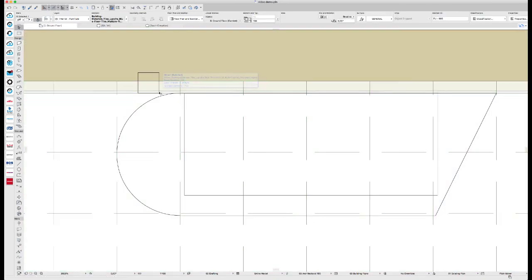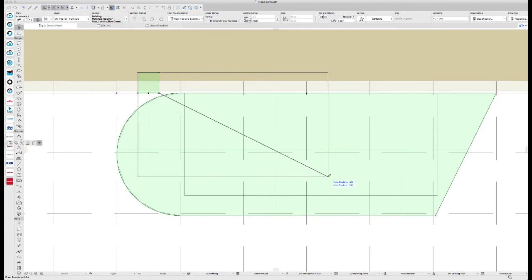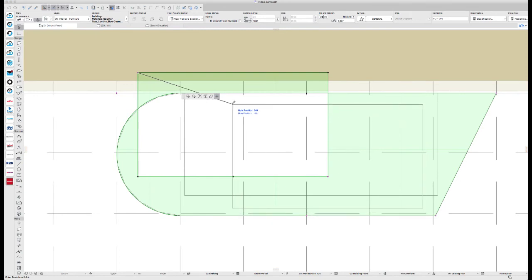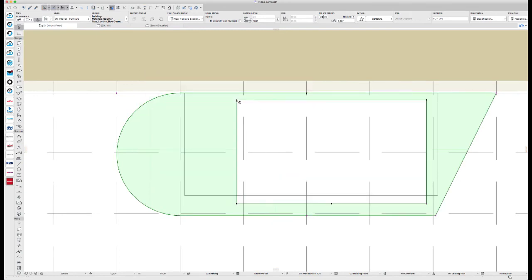You simply select the amount of openings you want within the countertop, and then you move its placement using the hotspot. You just simply confirm that in ArchiCAD, and then you have your object ready to add a sink or any other type of product which needs a hole cut in the surface of the countertop.